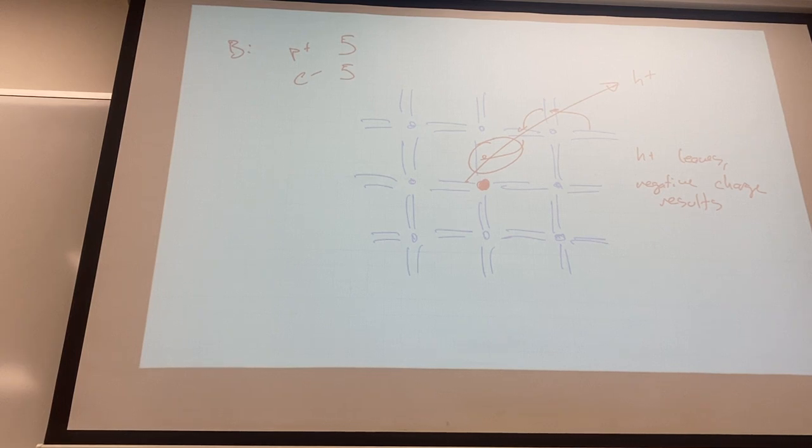This is going to be really important when we start talking about diodes, because we're going to have some materials that have too many electrons and some that don't have enough, and they're going to interfere with each other. The electrons and the holes are going to flow into each other, washing away these excesses of electrons or holes and exposing fixed-in-place positive and negative charges. Those form their own electric fields and then cause other problems with the electron and hole flows that we started with. This is how the PN junction of the diode ends up appearing: all of these forces counteract each other.